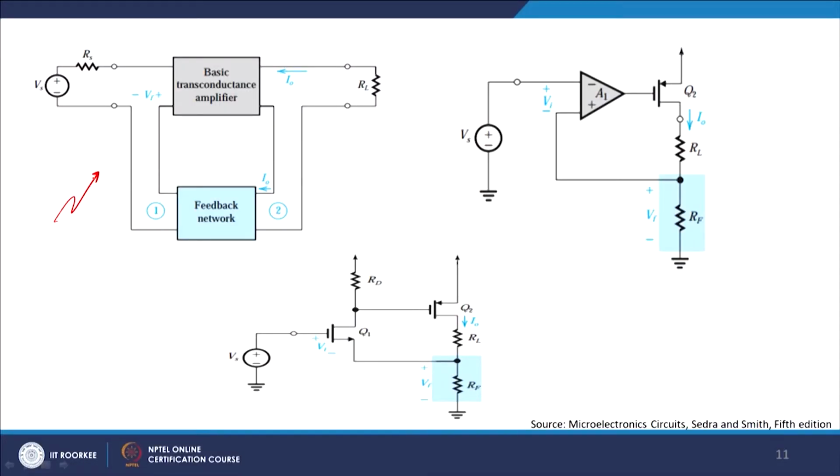This is an example of a basic topology of your series network, because both sides are series. You have a sampling side as well as your mixer side, both sides are a series combination here, and you have a feedback network coming here. If you want to do an analogy with real circuits, you have an op amp here which drives your Q2, which is a PMOS.